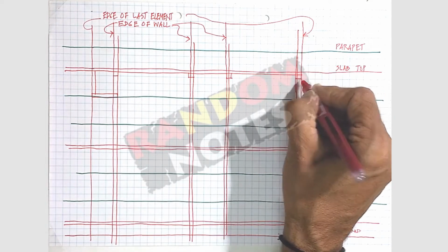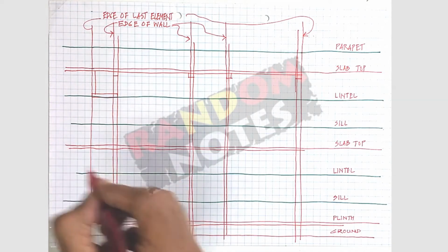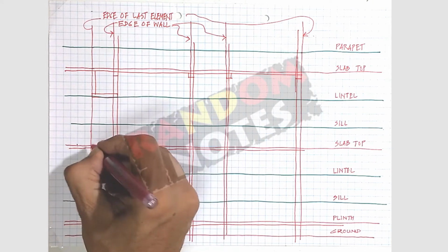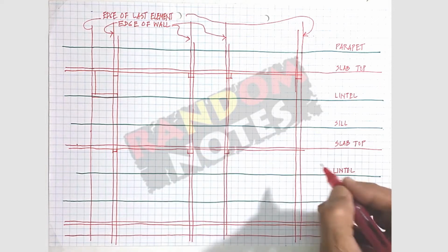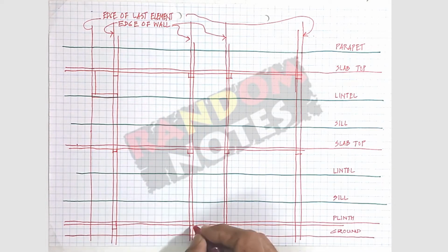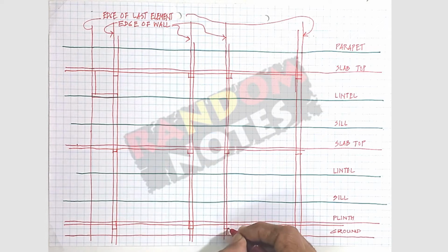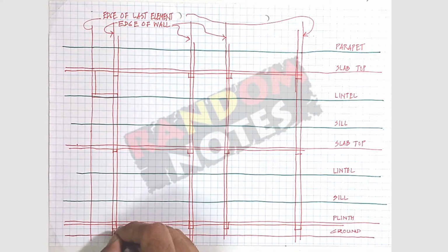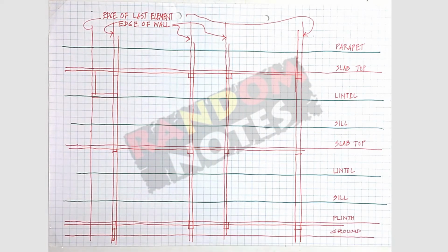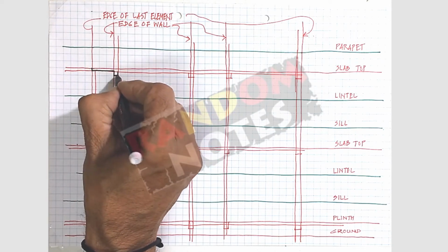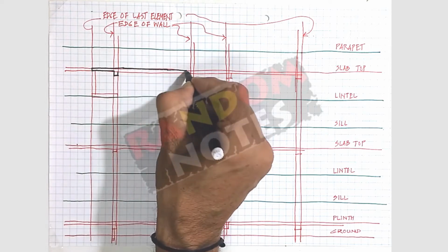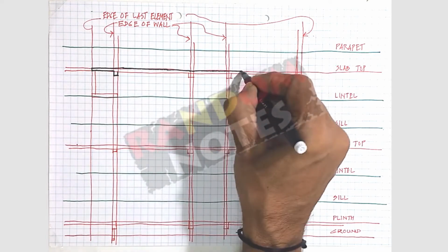Conventionally, the beams hang down from the slab. We also have inverted beams and sometimes flat slabs where the beams do not hang down as conventionally it is done. But to start, we will go by conventional practice only. Beams at plinth levels make a frame. Within this frame, filling is done so that the ground floor can be created. The periphery of this frame should be closed using a wall, a stone slab, or RCC curtain wall so that the filling in the plinth stays within.